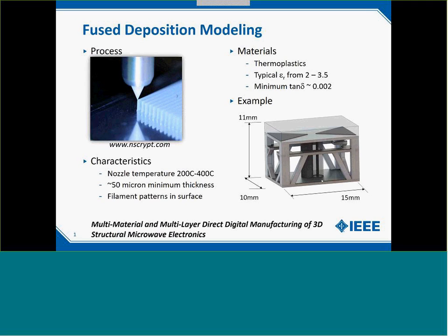And this is really important because it addresses the issue of surface roughness or surface profile, and that has a noticeable effect on the performance of microwave devices, especially as you go up in frequency. And pretty much regardless of the layer thickness that you achieve, you're still going to have some kind of filament pattern in the surface, and that can also lead to anisotropic effects.